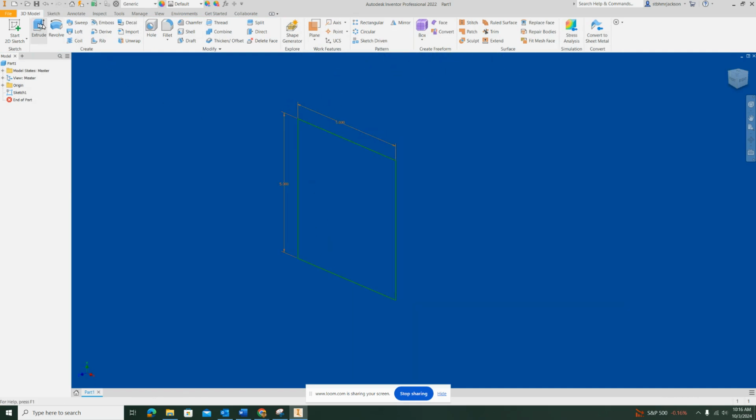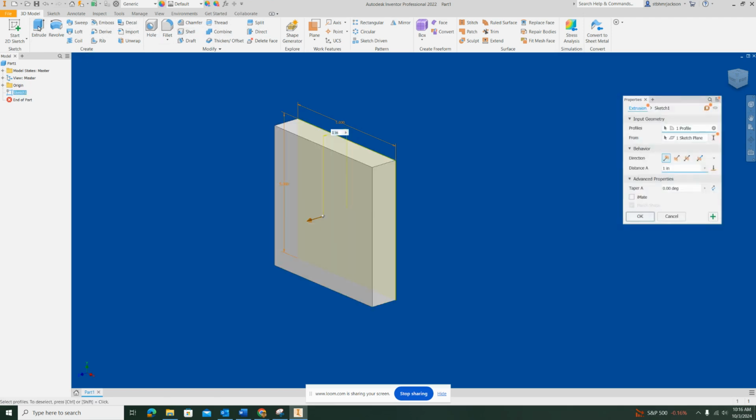and then we're going to use extrude. The toolbar that was a sketch toolbar, when I finished sketching, it went back to being a model toolbar. So now I can extrude, revolve, sweep, and so forth. Even do fillets, like you would do in AutoCAD, but actually on a 3D model. I'm going to do extrude, and it's automatically going to pick up the object because it's the only thing on the screen right now. If it doesn't, all you have to do is click on the rectangle, and it'll do the same thing. I'm going to put in 0.25 for my distance, and it's automatically going to change.